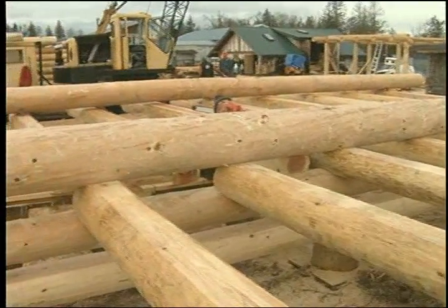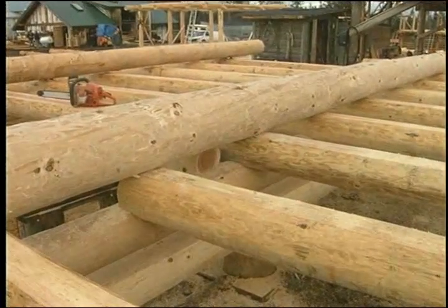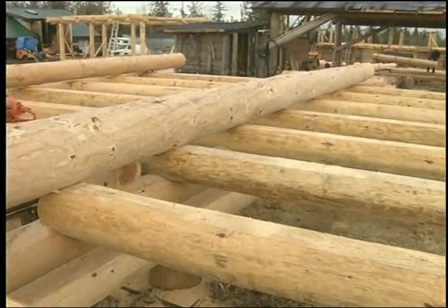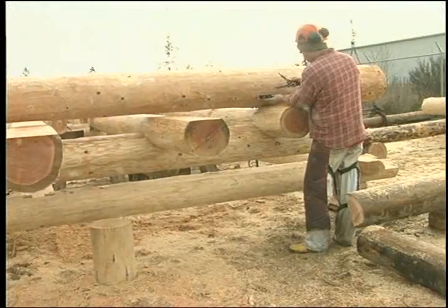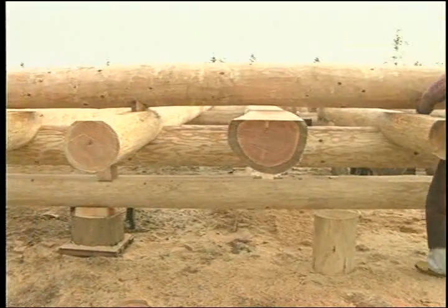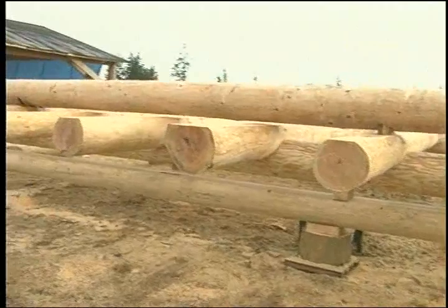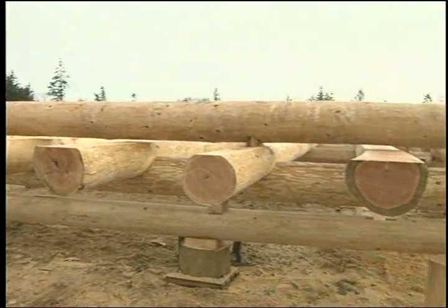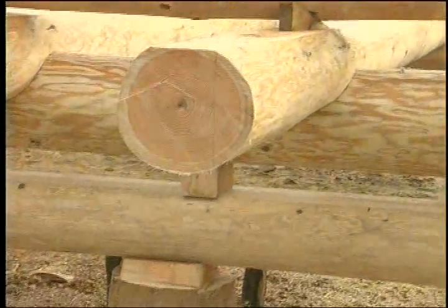Work very hard to obtain the required fit on the first operation, because adjusting and refitting this log can become a little frustrating. If you have removed the top logs of the wall to the ground in order to fit and level the floor joist, take this opportunity to set, scribe, and cut the flat on the top of the cap logs. If your building is large and the cap log long and heavy, it may be a good idea to block the setup at the center to keep everything in line.